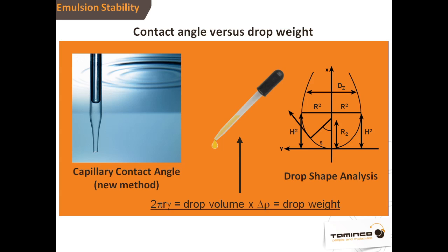It's a good method. It's prone to quite a few errors. There's a lot of physical things that happen with ejection of the drop too rapidly from the orifice, but it's a great way to start, just to collect some sort of basic initial numbers for a liquid-liquid interfacial tension. There are other ways. Probably the most sophisticated method of doing this is to use drop shape analysis. There are instruments that are sold to do this on a routine basis. And then there's another method.